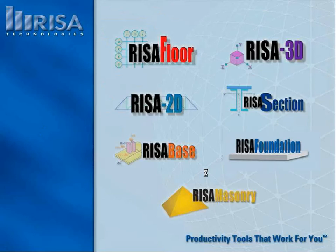And we also have another program called RISA Floor, which I mentioned we would focus on as well today. RISA Floor is a building analysis software, so it helps you design your entire building. You lay out your building floor by floor and carry the gravity loads down your building to design all of the building elements. In RISA Floor, we designate things as gravity or lateral, and then we take the lateral elements into RISA 3D. So those two programs actually communicate.